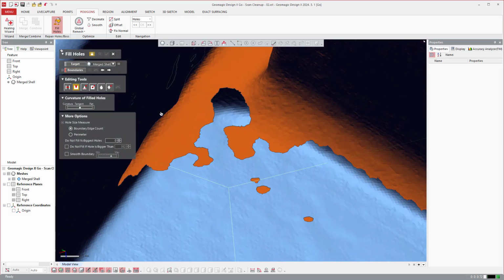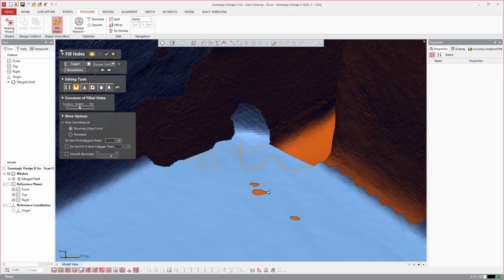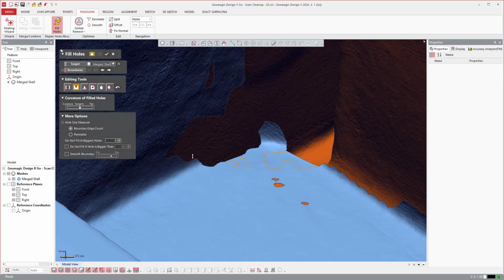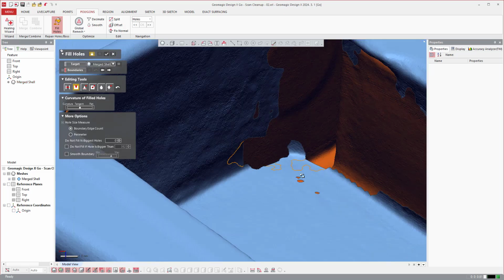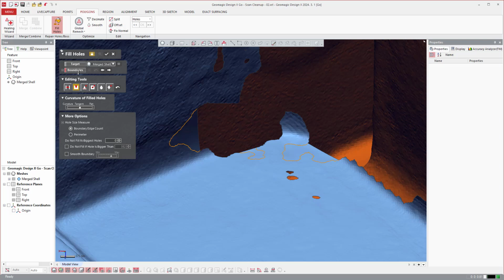So just to reiterate, if I wanted to do a fill partial here, click, click, select the side, click there, select the side, just like that. It helps to look at the curvature and fill based on that. This is all a flat area, kind of flattish, so you see what I'm doing there. And from there I can select boundaries.